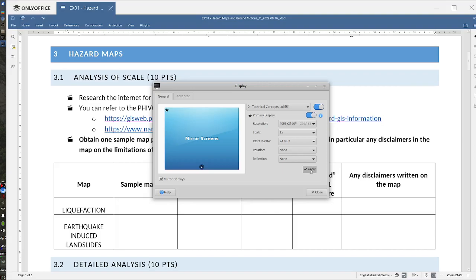So most accelerographs are ideally placed on a bedrock foundation, because it's the easiest to correct, no? Bedrock usually is more or less consistent in terms of behavior. So this value is what we call uncorrected or bedrock condition.